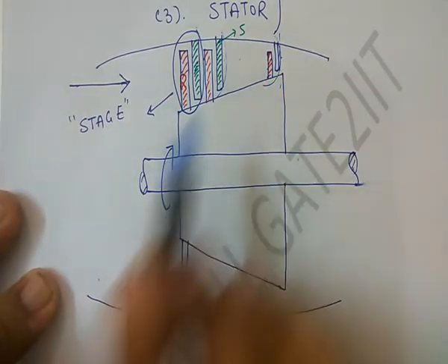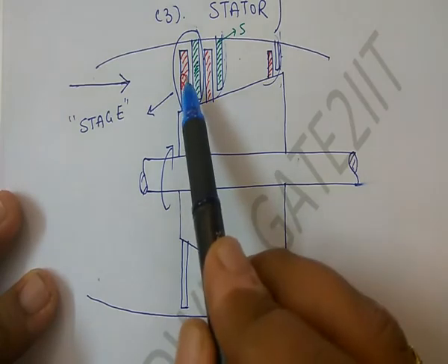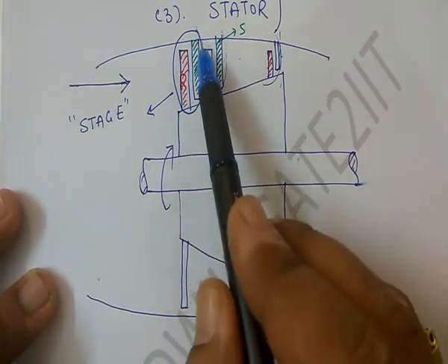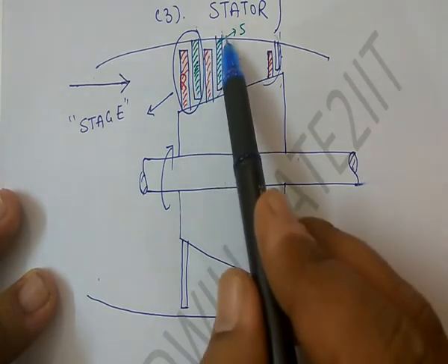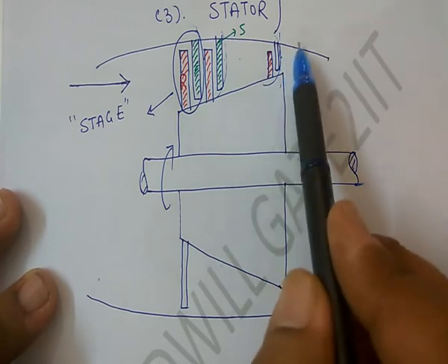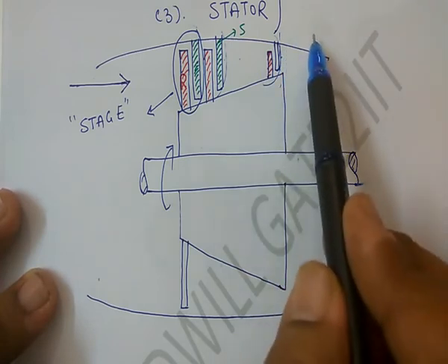Alright, so this is the reason why we are using rotor blades, stator blades, rotor blades, stator blades. Hit the air, increase the pressure. Hit the air, convert this kinetic energy into pressure rise. In the end, you have the overall effect of the compressor.